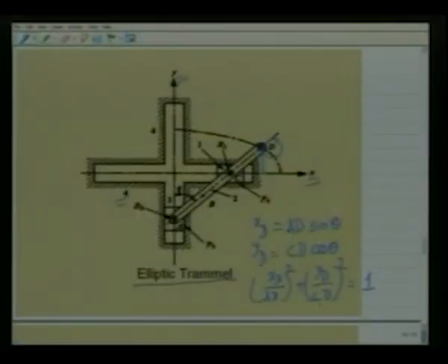It must be pointed out that there are 3 points on this rod AB which are exceptions, namely this point A, which generates a vertical straight line because of this prismatic pair. Similarly, this point C generates a horizontal straight line because of this horizontal prismatic pair.